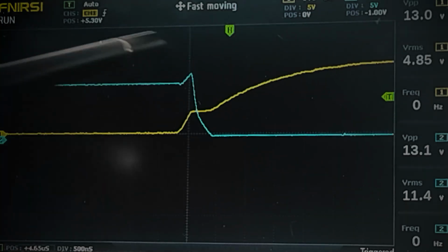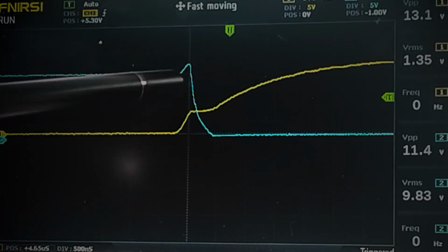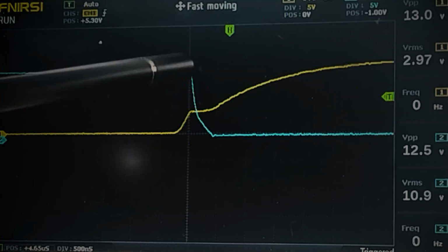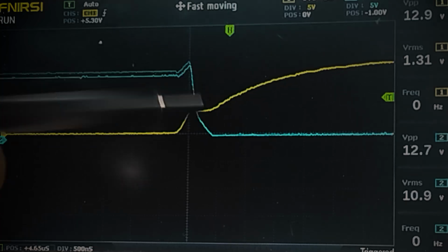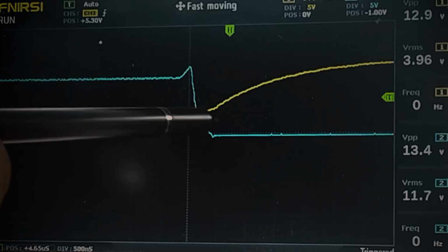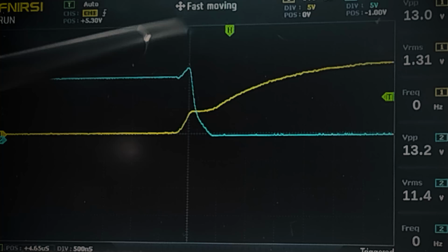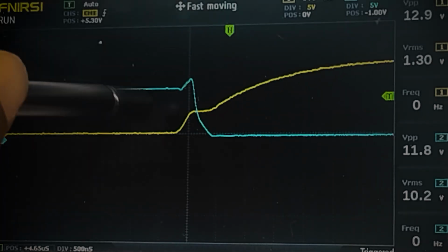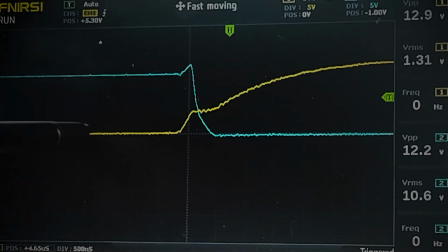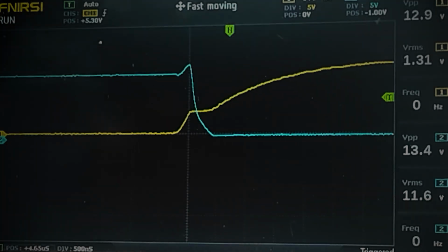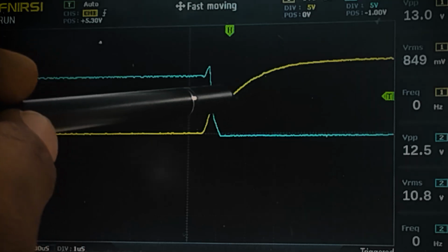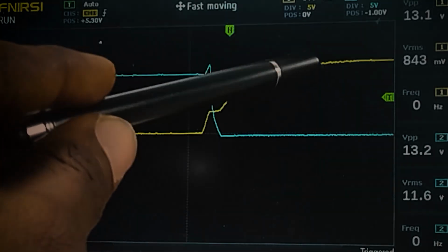This is the area where it switches on. So around this place, from here to this part, would be our MOSFET within the linear region, where it's not completely on or completely off. So if we look at the gate voltage, we would see that we have a ramp. This ramp is what we're talking about now.